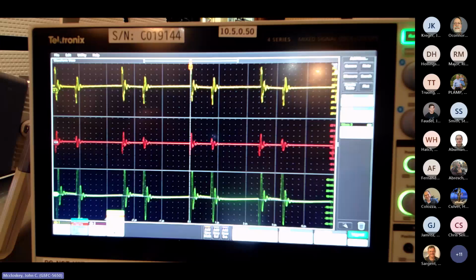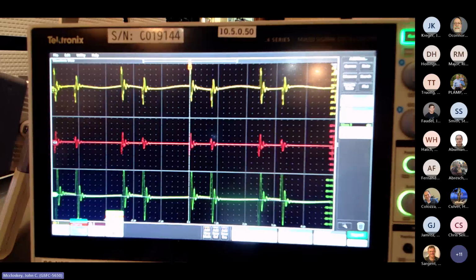I believe each cable can take about an hour. So doing a CS114 scan on each individual cable just for common mode can take about an hour. So if you've got a lot of cables, that can add up. You've got a couple dozen cables, that could be a couple days just to do CS114. But at least for an early diagnostic, using this simplified setup, you can do each cable in under 10 minutes. That's a pretty valuable tool to have in your belt.